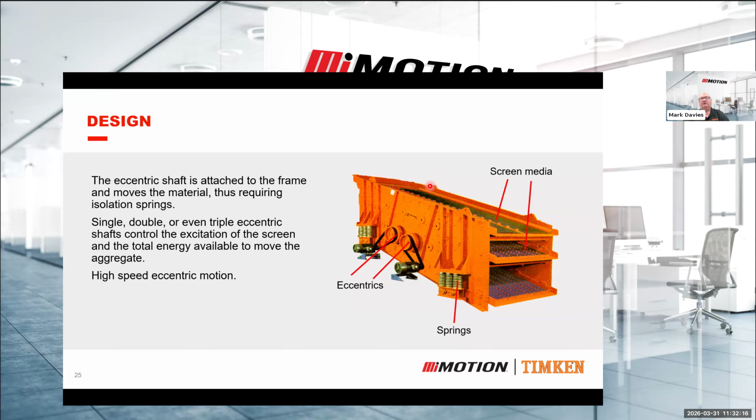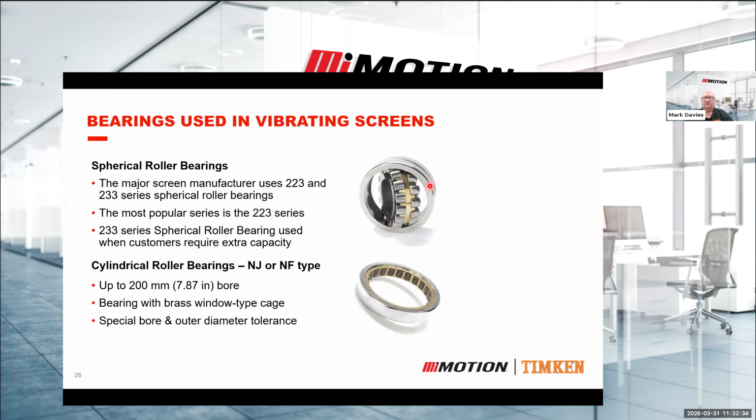So there's a big difference between screening coal compared to iron ore. Iron ore is a much heavier product, so it's a much larger screen normally, and more mechanisms to make the screen bounce that amount that they need. But the bearings are really critical. You cannot put a standard spherical roller bearing into a screen. It's the wrong specification. It will get damaged very quickly, and it will only last a number of hours.